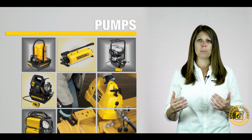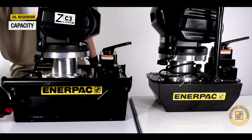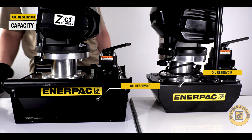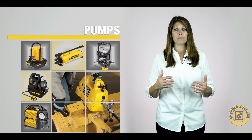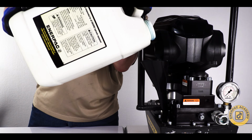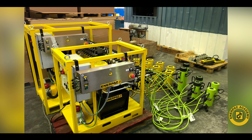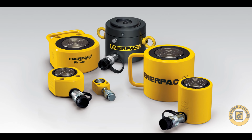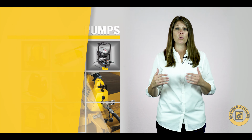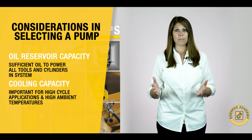Most industrial pumps have an integrated oil reservoir that has a specific oil capacity. Oil capacity must provide two things for your system to work properly. Firstly, there must be enough oil to support your tool system requirement. This means enough oil to support the tool being operated or all cylinders in the system. Secondly, the oil and reservoir can be used to provide a cooling capacity to the system.